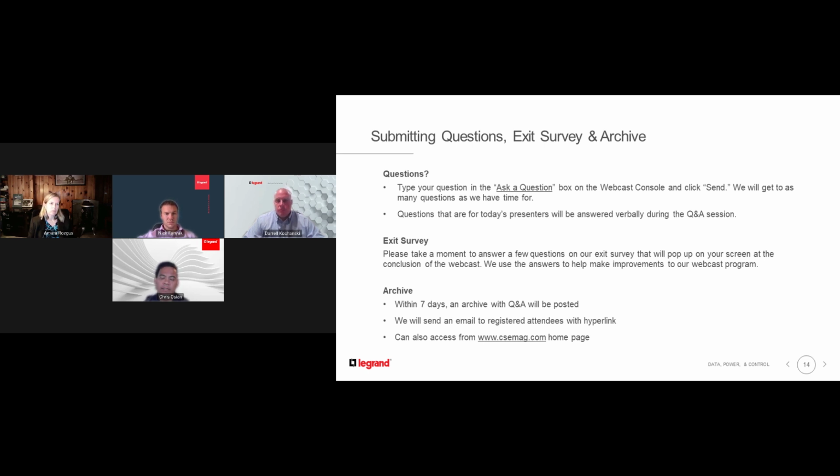And to add to that, we can also monitor at that point. We can add a monitoring solution to allow you to get visibility on how much power is running through the busway at that point. We also have monitors available in the tap box location as well, if you're interested in some sort of load profile of a device.